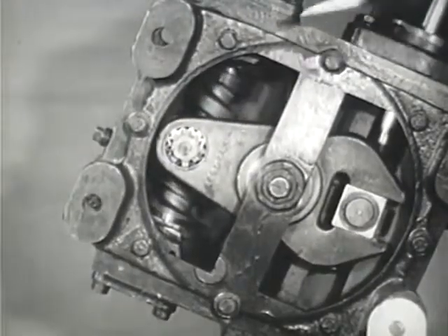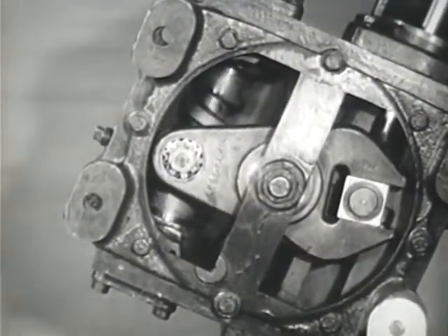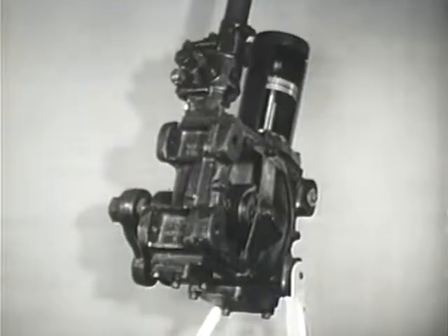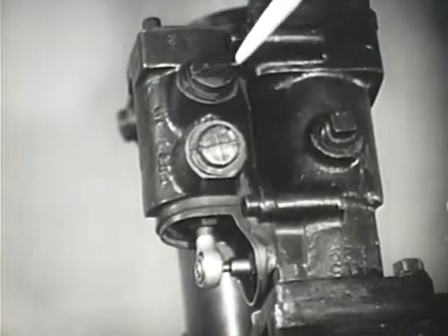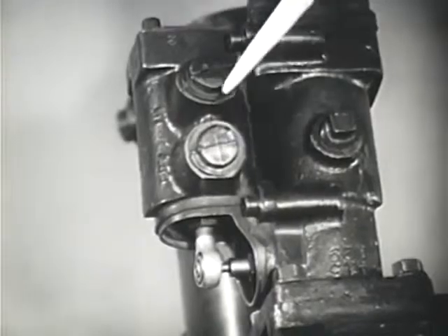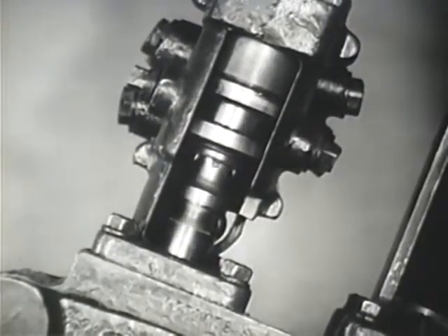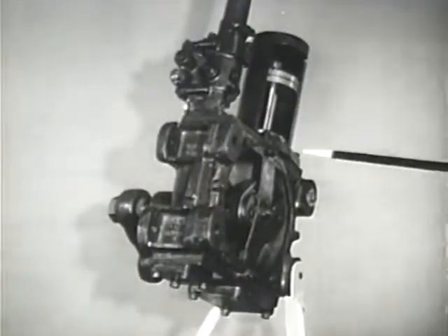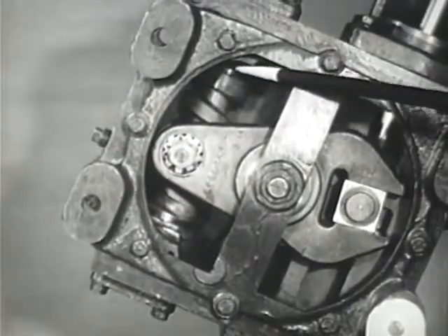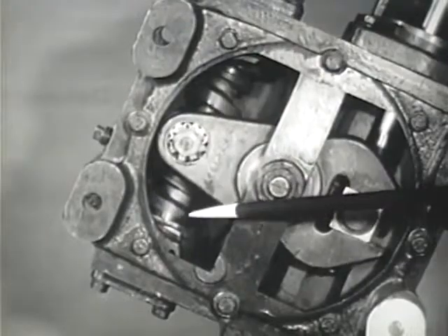In order for the hydraulic assist mechanism to operate, the steering cam must be able to move up or down to actuate the control valve. A spline connection makes this possible. The cam is held in center or neutral position by a spring at either end.